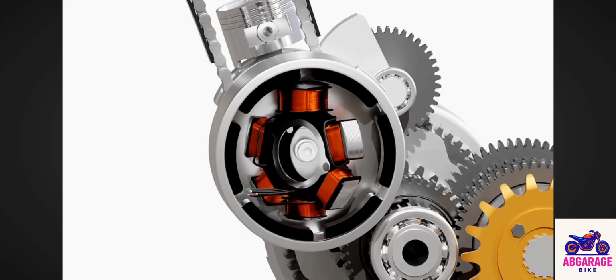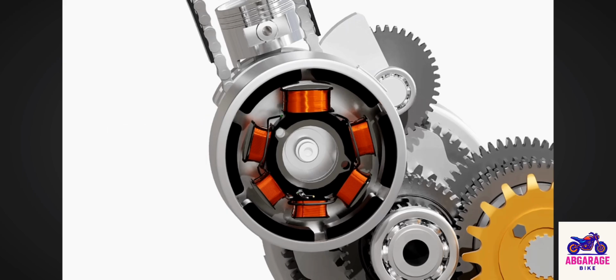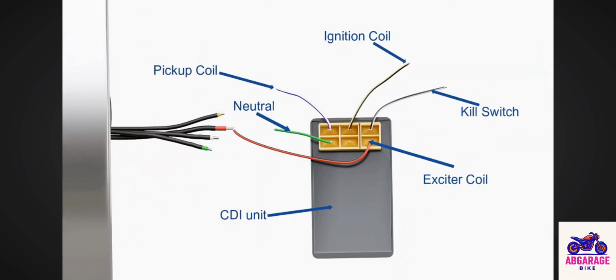The output for the ignition purpose is received from the exciter coil. This coil has a denser winding of thinner wire than the other coils to produce higher voltage for the ignition. This voltage is supplied to the CDI, as shown here.